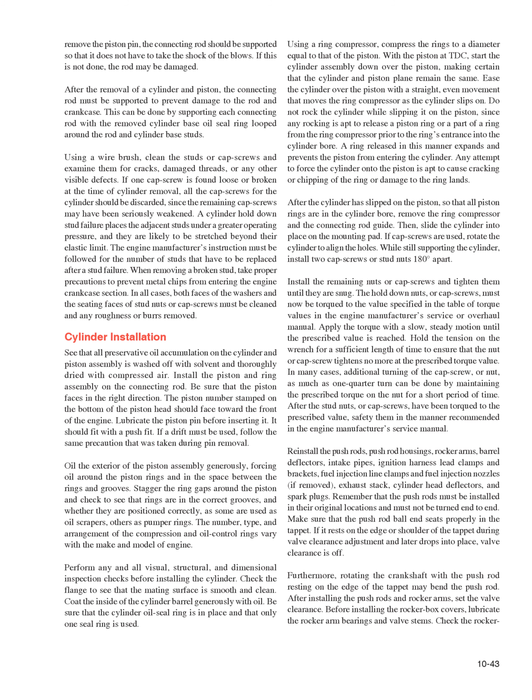Do not rock the cylinder while slipping it on the piston, since any rocking is apt to release a piston ring or a part of a ring from the ring compressor prior to the ring's entrance into the cylinder bore. A ring released in this manner expands and prevents the piston from entering the cylinder. Any attempt to force the cylinder onto the piston is apt to cause cracking or chipping of the ring or damage to the ring lands.